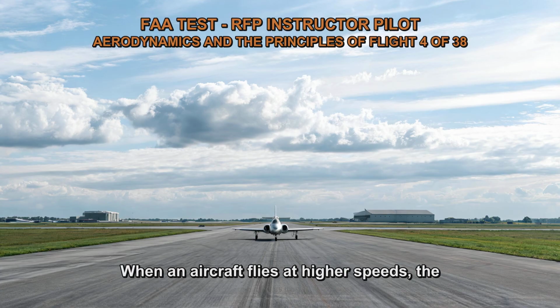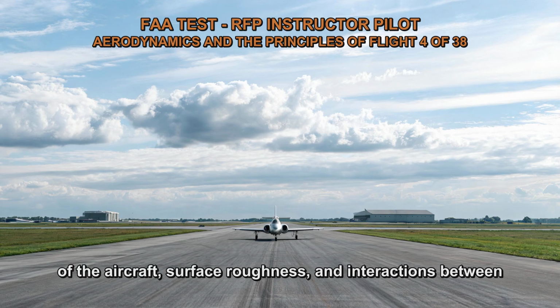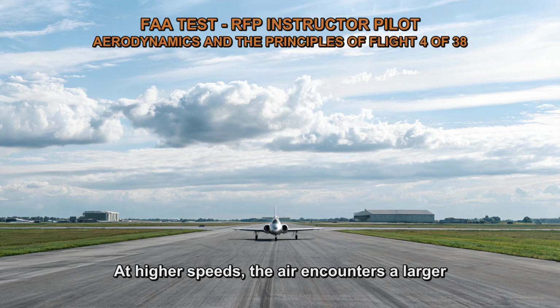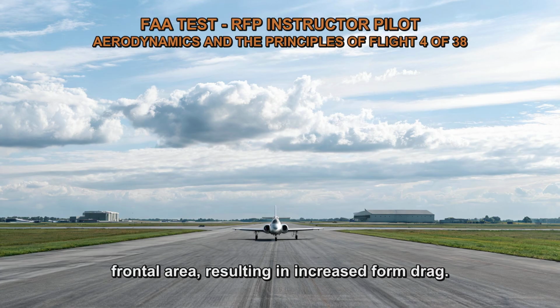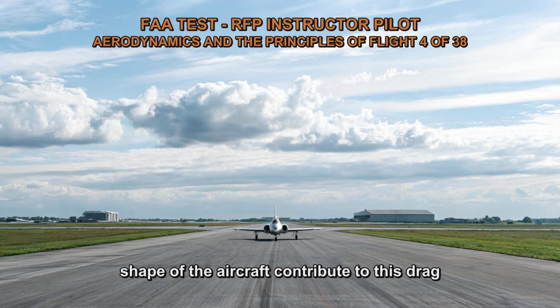When an aircraft flies at higher speeds, the airflow encounters more resistance due to the shape of the aircraft, surface roughness, and interactions between different components. This leads to an increase in parasite drag. Form drag is caused by the shape of the aircraft. At higher speeds, the air encounters a larger frontal area, resulting in increased form drag. The pressure differences and turbulence created by the shape of the aircraft contribute to this drag component.